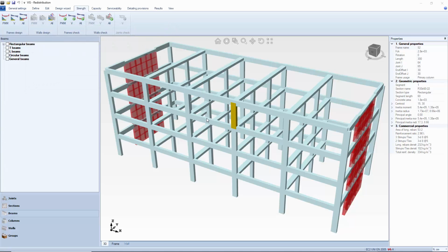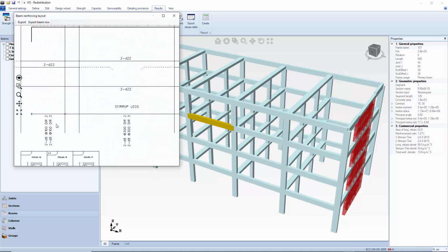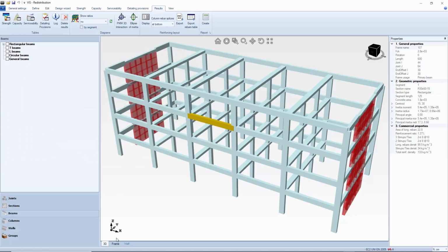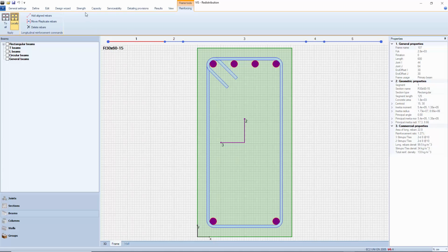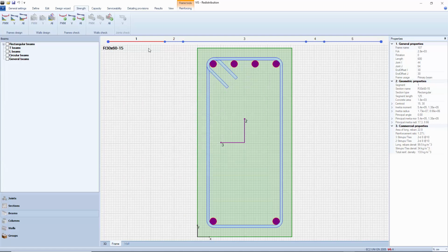Okay, now say you have already designed the beam and assigned some reinforcing and want to check it. Just follow the same procedure as before, clicking on the check buttons instead. In place of required areas, you get demand capacity ratios at the various segments along the beam.